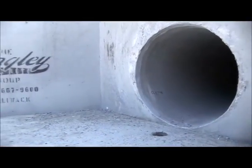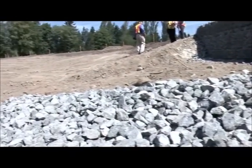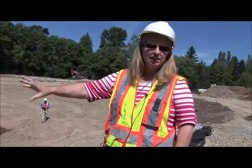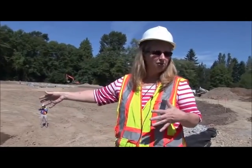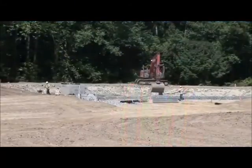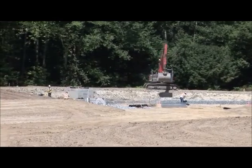One issue with detention ponds is that regular maintenance is required for them to function. They must be dredged, and contaminated sediments need to be properly disposed. If we ever need to clean the inlet, because that's where the sediments will come out, we have a platform we can do it from here. We design these things now not for your 5-year storm, we design it for your frequent annual storms. The frequent storms are what causes the erosion, and that's really what you're doing a lot of this for.